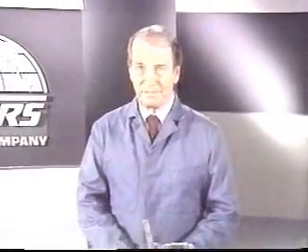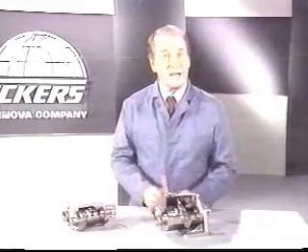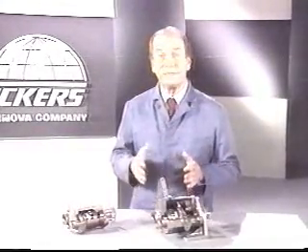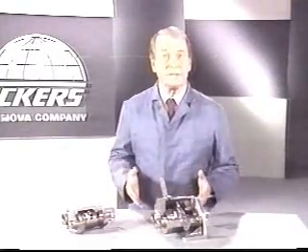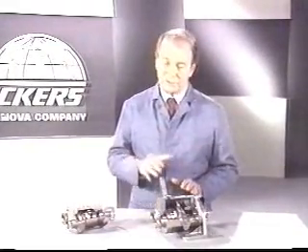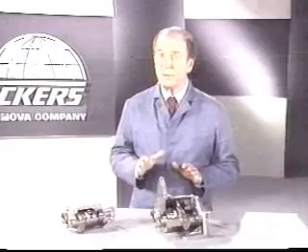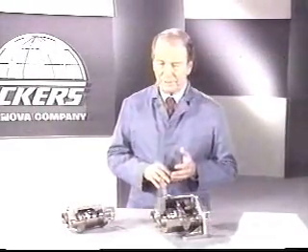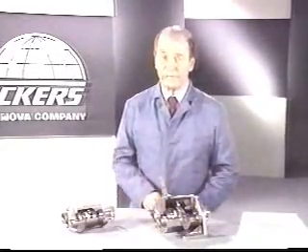Okay. That concludes our discussion of hydrostatic transmissions. In summary, these transmissions offer some important advantages. They're flexible and easy to operate. They have high horsepower in relation to package size and weight. They can be stalled without damage. The low inertia of their rotating members permits fast starting, stopping, and reversal with smoothness and precision. The output shaft speed can be varied over the full speed range in either direction, with constant input shaft rotation.